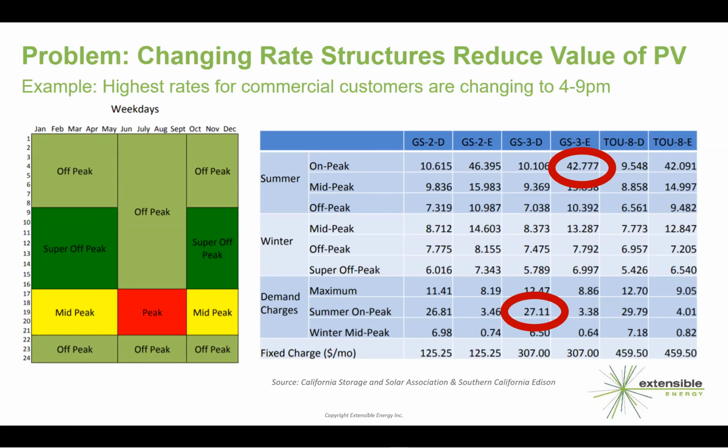But neither of these is very friendly to the solar provider, because all of these are based on a time of use period where the highest rates are from 4 p.m. to 9 p.m. after, as Jeff was just showing, the solar production is either past its peak or zero. And so if you can reorganize your usage patterns slightly so that there is more usage during the time when rates are cheaper and solar is cranking, then you have a greatly improved set of project economics.